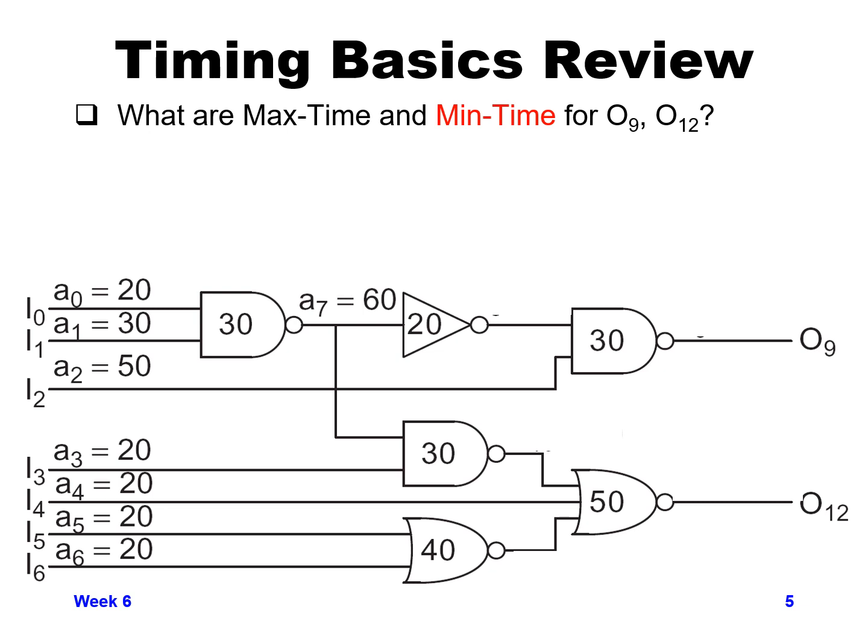Now we only have a single input to the inverter. It's coming in at 60 picoseconds. It has 20 picoseconds through the inverter, so the output of the inverter is going to have a max time of 80 picoseconds. Next, let's go down to the NAND gate below the inverter in the second column,